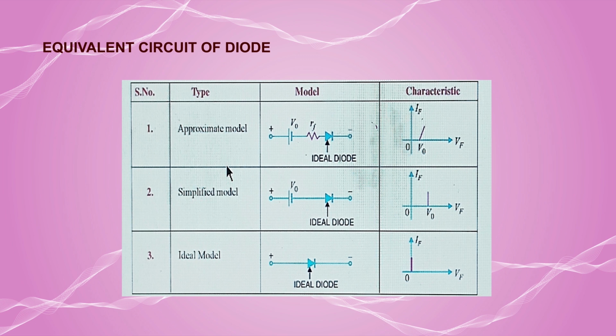will show the approximate model of the diode. In this, we can see the VI characteristics show in the forward bias region a characteristic of exponential nature. So, for a particular instant the diode will be non-conductive, and when the knee voltage is overcome, that is the amount of voltage here shown as V naught, beyond that the diode becomes conductive and current starts flowing in exponential nature.